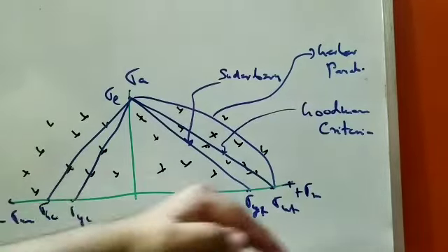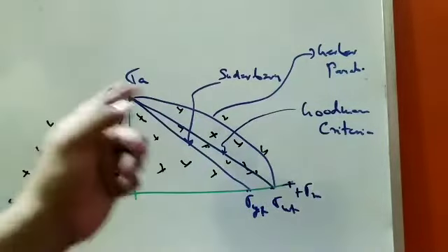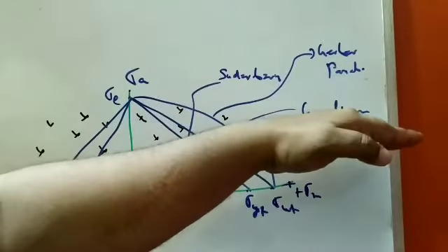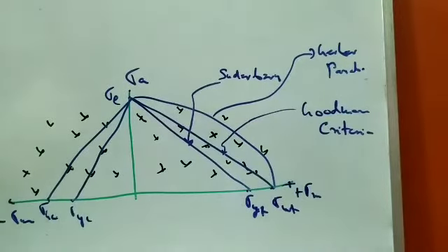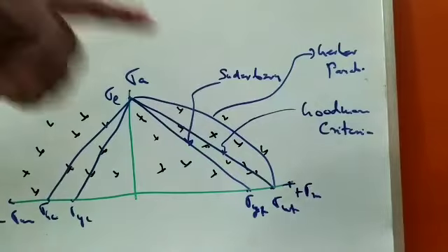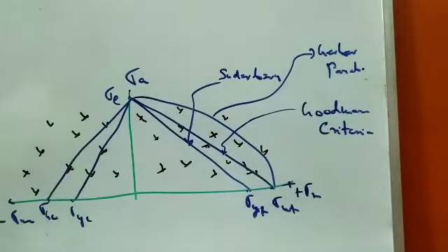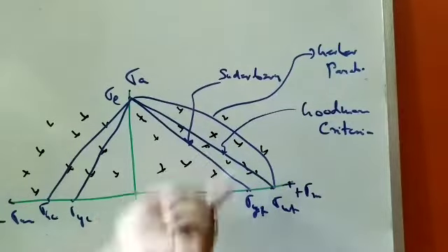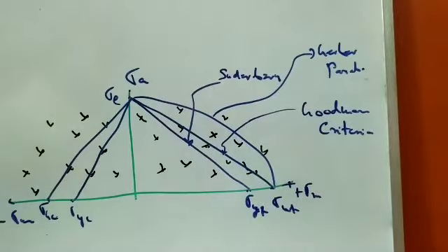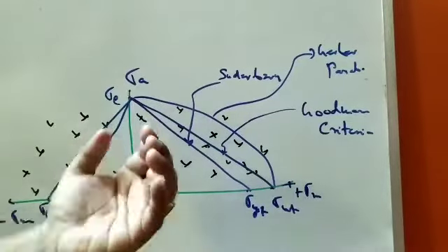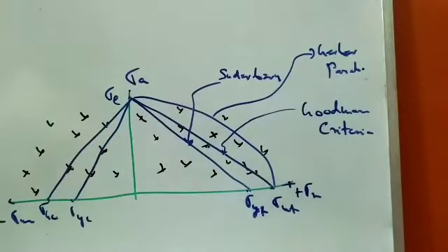Goodman criteria is maximally used because it is used in most designs where both endurance strength and yield strength are there, and some considered the Soderberg criteria. But Soderberg criteria is more conservative, because it is more away from failure. So some consider Soderberg an important criteria for failure.